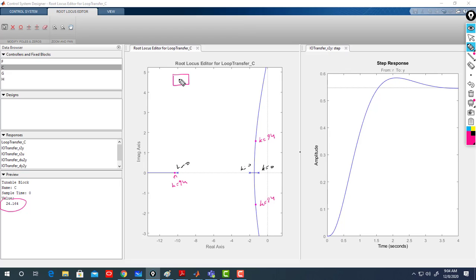C is 24, and you have the plant, which is the open loop transfer function. Here is your system. That's the reference. That's y, minus, plus. Okay, I have filter equal 1 here and unity feedback. So you are looking at the step response. You are looking at y by applying a unit step input.